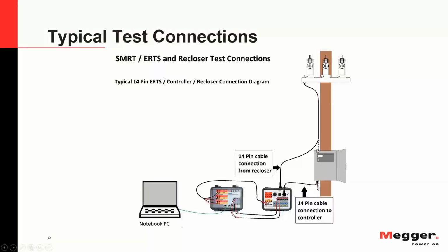But you can also use the breaker status signals that come from the breaker to feed them into the relay, so that the relay has the feedback from the breaker that it needs to perform its operation. Remember that reclosers are very sensitive to breaker status. They are very sensitive to discrepancies between the breaker status and the status of current through its analog inputs.